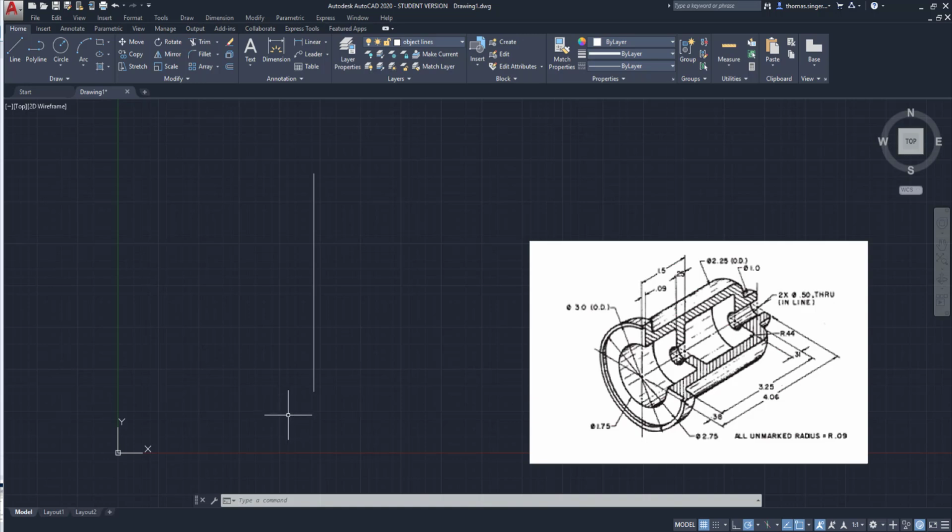So we can begin drawing the shape as a rectangular oriented shape, and then work with the specific details. This line itself is going to be our center line. I just drew a line here. We're going to grip it, go up to our layers, and select center line so it becomes our center line shape. It's a quick and easy way. You don't have to switch layers to draw the line. You draw it as part of the object layer and then just apply the center line itself.